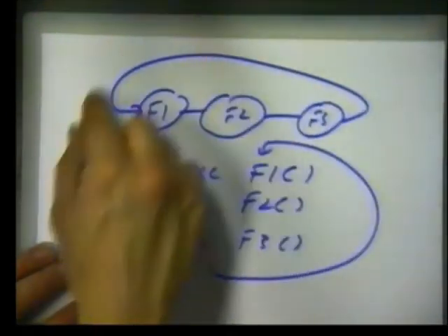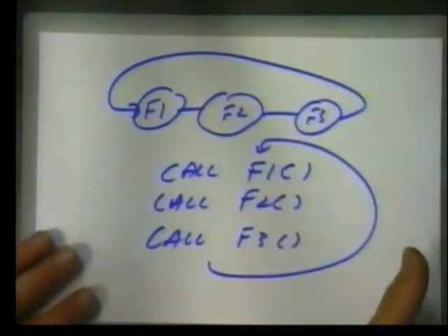You can have a background function that fills in the gaps, and that can spread forever. But if you've got real-time functions, when they're scheduled to run, they must finish. So this structure, just going round and round the routines, is perfectly valid. And the vast majority of real-time systems, the operating system, is no more than a series of threaded codes calling subroutine 1, 2, 3, 4. You may get a series of logical decisions in it, so you can get some signals and flags to make it a bit cleverer.